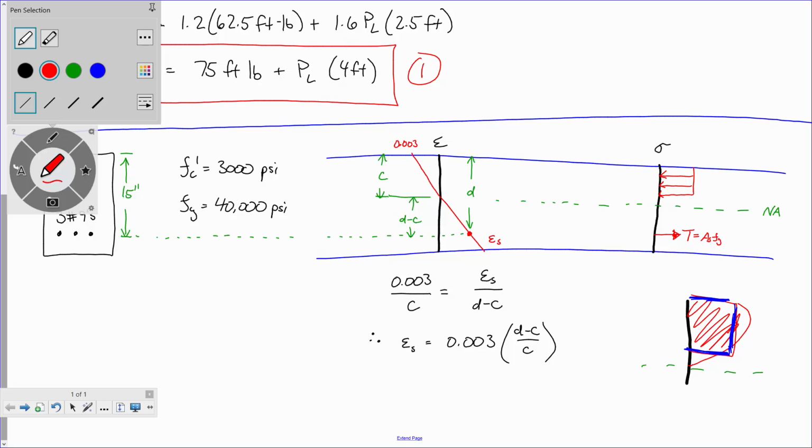Okay? And what is the width of that stress block? It's not f'c, it's how much f'c? 0.85. And that is always true. Remember, that's our empirical relationship that relates this nonlinear area. That's the relationship that will give us an equivalent moment.